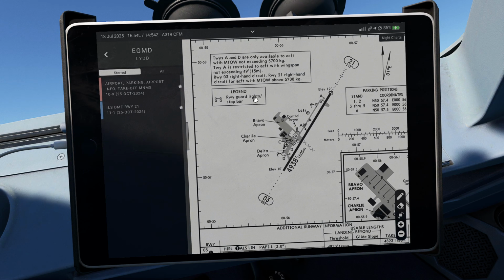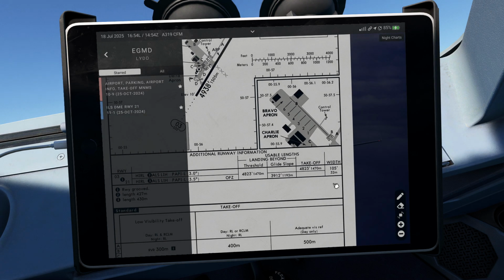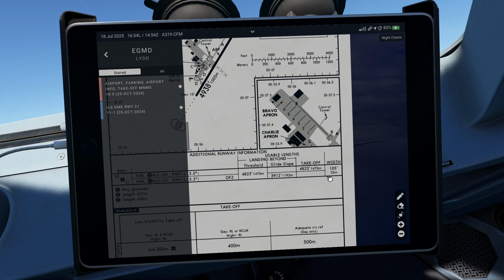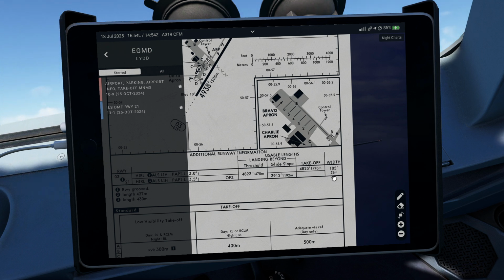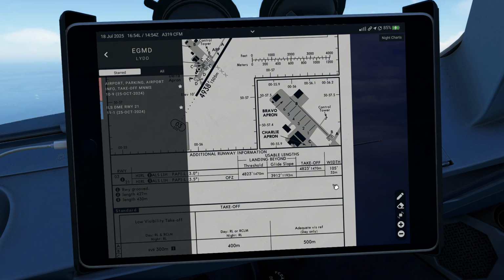These are mostly the limitations: the parallel taxiway is not available for the aircraft. Another is that although Airbus certified the A319 for runways with a width of 30 meters or above, 32 meters is marginal.